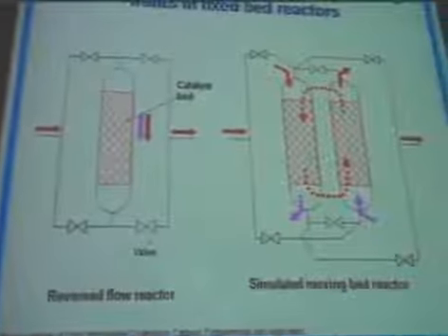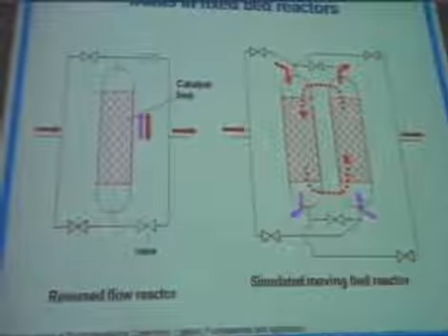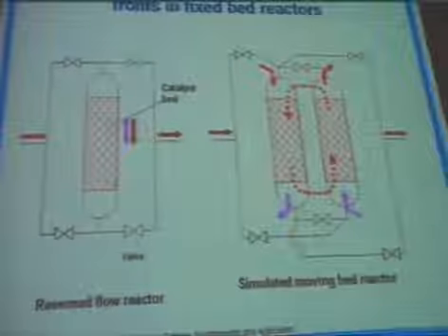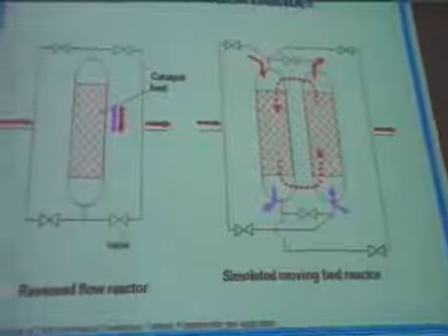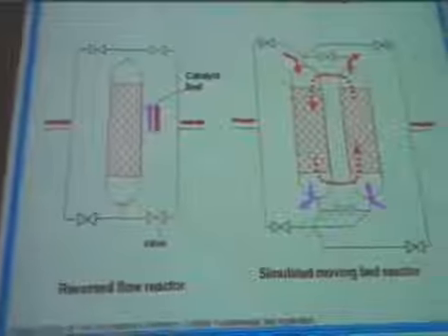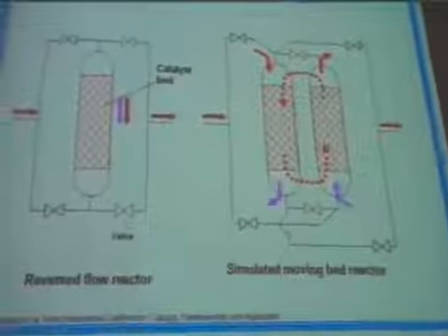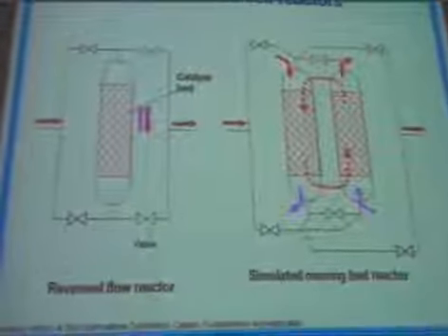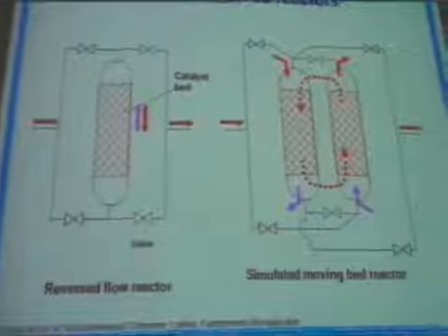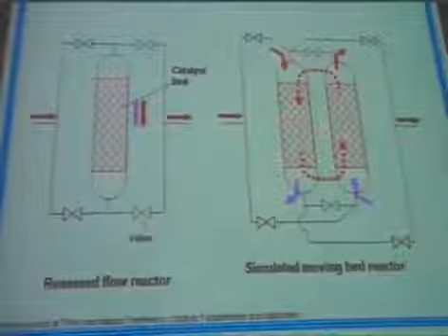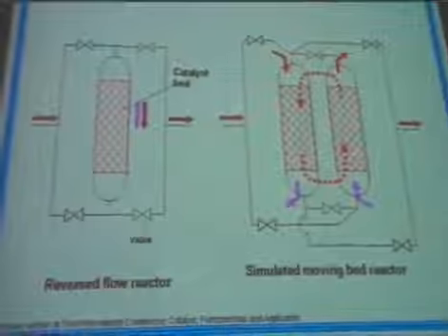During the last maybe 10 years, a lot of works were published where people propose different technological schemes that allow them to have this hot spot inside the packed bed of the catalyst by different configurations of the technological scheme. But the idea is the same: to have this hot place inside the packed bed of the catalyst under conditions when the inlet temperature is relatively very small.